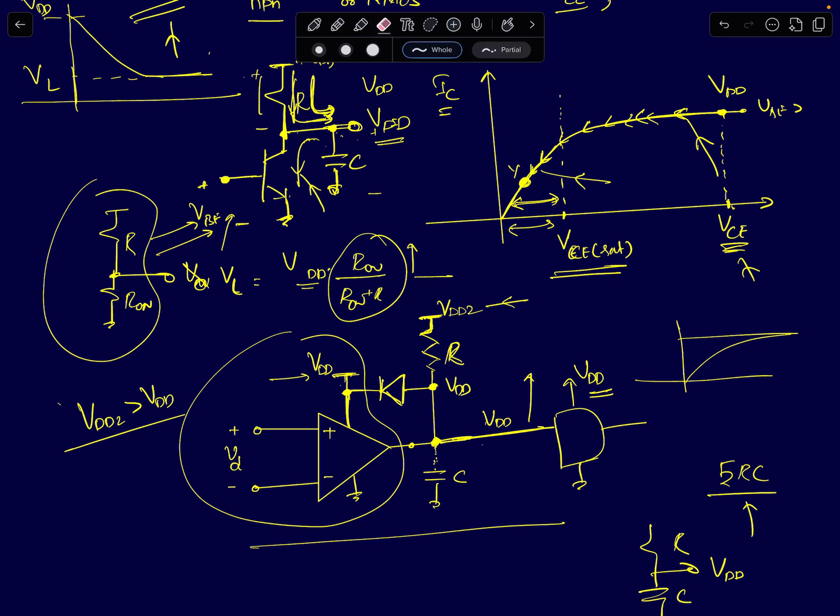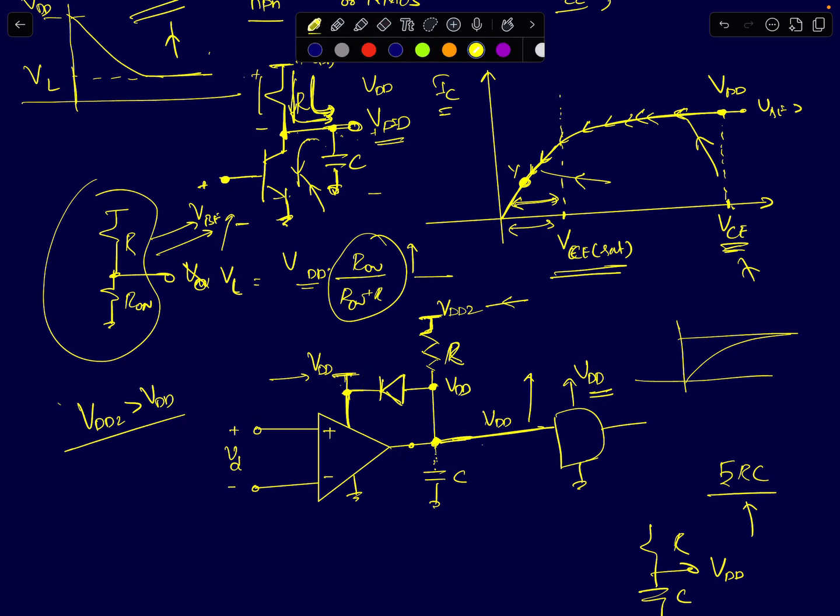So now if you see, remember for a comparator, for a discharge path, the transistor here will be cut off. If you guys can remember the first slide, the first point that we discussed in the mathematical model of a comparator for an open collector output based comparator, we said that for a charging path, this guy will be cut off, right? There is no discharging path active. So if you connect this node to VDD2, ideally this node voltage will just charge to VDD2.